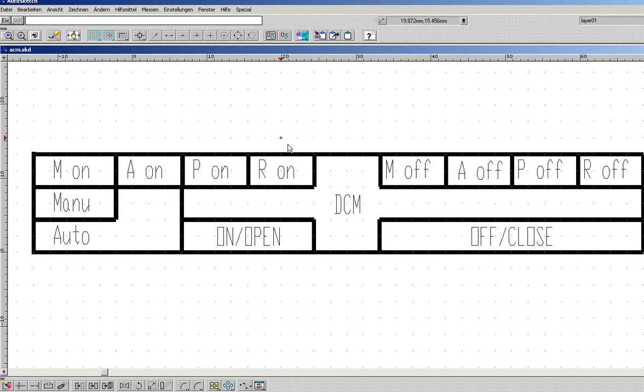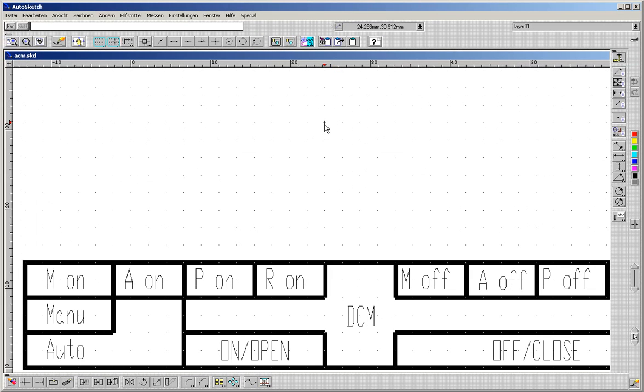You need to save this DXF file as DXF release 12, and additionally, very important, there needs to be no grouped graphical information in it. logi.DOC will not modify any text styles and will not modify any properties of lines, so the graphic will be inserted into the FBD completely independent from the DXF tool. Here you can see a last full view of this DXF file.